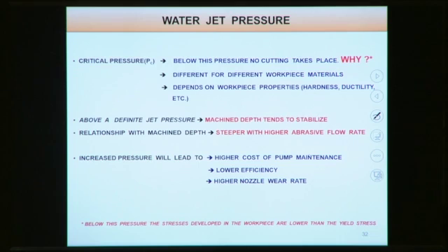Increase in pressure also means, as we have seen, that with the increase in pressure your metal removal rate or depth of cut increases, but only up to a certain limit, some optimum level of pressure. Beyond this critical pressure, what happens? There is a decrease in metal removal rate.